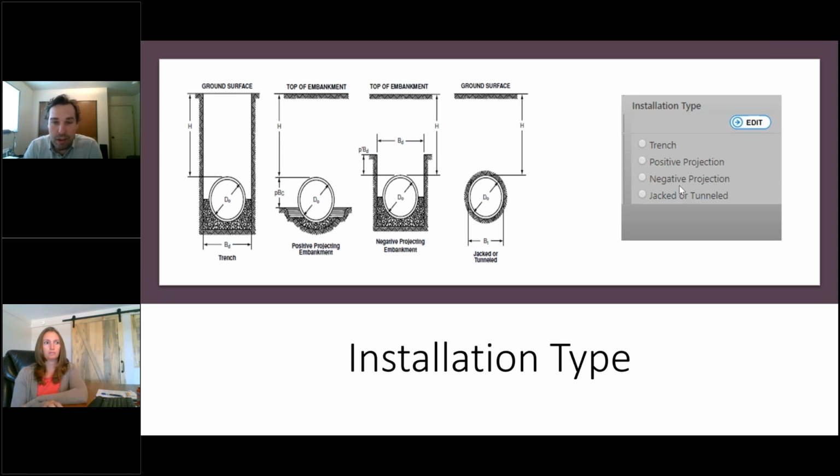But I typically always include it just to be conservative, even on 12-inch diameter pipe where it's not going to really make a huge impact to the actual design. I almost always include it. Yeah, that's what I was going to say, conservatively, you can always include it. If you know for sure it's going to be more of a dry culvert, then you could not include it.